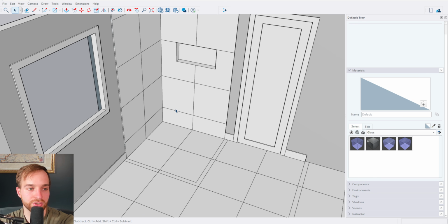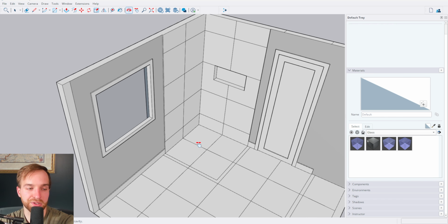Something else we do like to do, I know in this example, I did use 1 foot. Oftentimes with our first row, we might do something like 10 inches. And that way, this first tile here, the other half of it can be used for this one. And instead of this being 2 tiles and wasting 50% of it, this is now 1 tile and this is now 1 tile, right? So I could count it that way if I wanted to be really efficient.